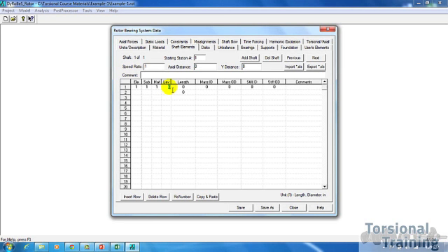Now you type 0, because what the level tab does is give you a vertical distance. In this case, since we're building a simple shaft, we're not going to be adding any shaft above or below the shaft that we're working with, so ignore that and leave it at 0. Our example shaft is going to have a length of 10 inches. Leave the mass ID, which is inside diameter, at 0, since we're modeling a solid shaft and there's no inside diameter. Now the mass outside diameter, make that 8 inches.